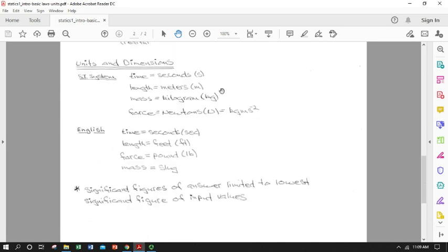Okay, speaking of units, there's two fundamental unit systems. For most scientific work, especially mechanical engineering, you will be using the SI system, Système International, otherwise known as the metric system. So that has standard time in seconds, which we won't use as much, length in meters, much more relevant for the course, mass in kilograms, and force in newtons. And the analogous moment would be Newton meters. You will get about maybe 30 to 50% of your problems in SI.